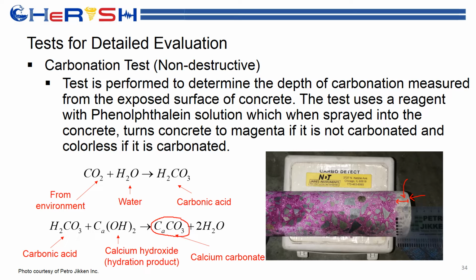Now, in terms of the reinforcing bar, what carbonation does to concrete is that it really damages what we call the passive layer in concrete. The passive layer is the layer between concrete and the reinforcing bar, and this layer has a very high pH. Now, due to carbonation, this pH level is reduced to a level wherein it would already initiate corrosion. So that is why carbonation is really detrimental to reinforced concrete.